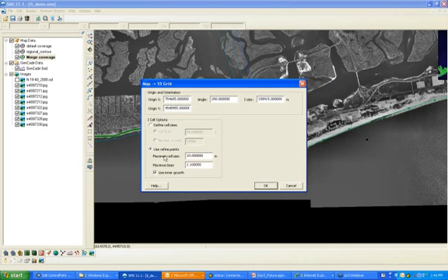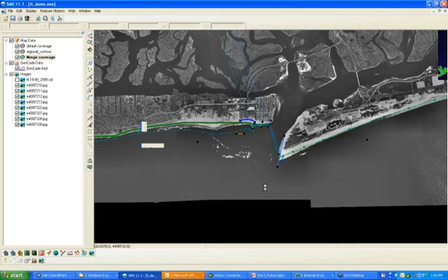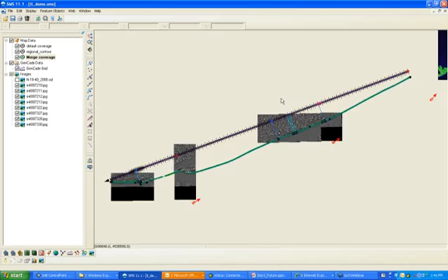I'm going to change the maximum cell size to 200 meters, and I'm going to change the maximum bias. Again, this is how much each cell is going to grow, to 1.08. And I'm going to say I do not want to use intergrowth, so I'm going to uncheck it. And I'll click OK. So now we're actually going to have a different grid setup.